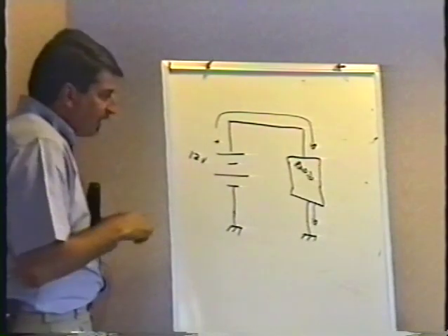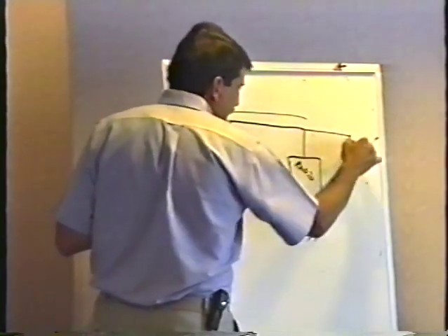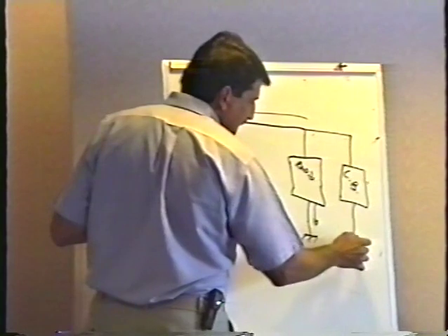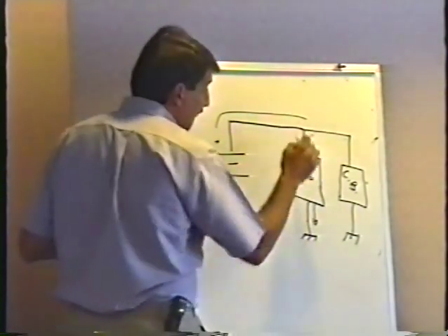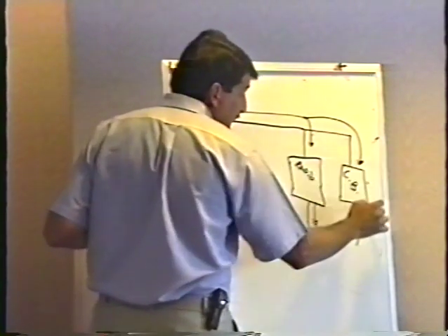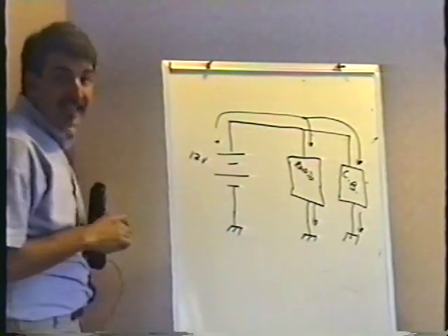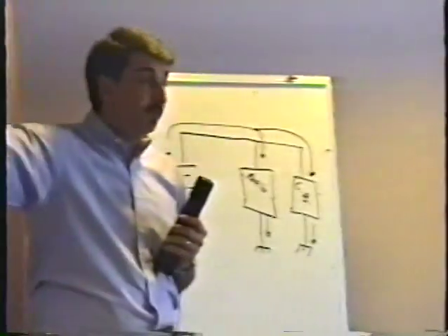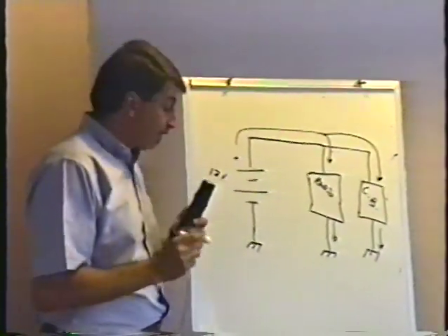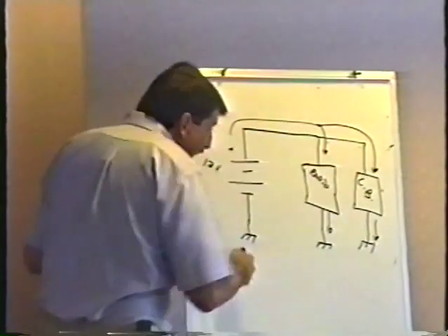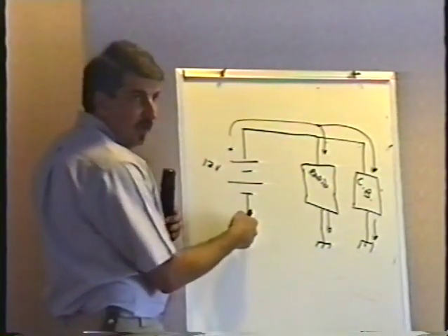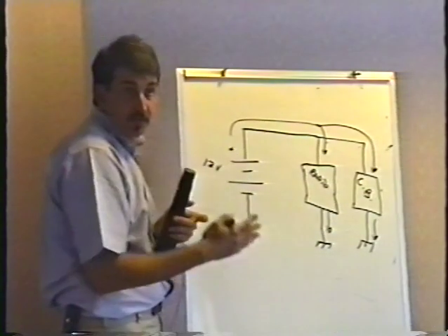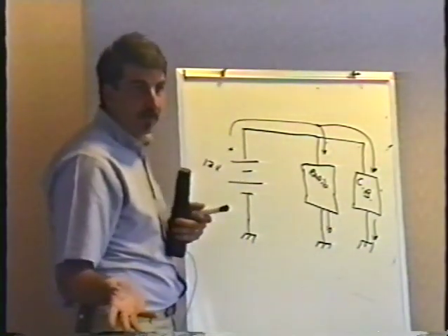When I draw ground in 2 or maybe even more different places, like, for instance, it not only goes to the radio, but I've also got a CB rig, right? That side of that would also be grounded, right? That's the return path. The current flows into the radio, but current also flows into the CB. The return is back through ground. There's lots and lots of things in a video game, a monitor, a pinball, whatever, that are connected to ground. And instead of having a wire going back to a central ground, which would be really complicated and the schematic diagram would be a mess, they put a ground symbol everywhere that it goes to ground. But everybody can see that these are all connected together, correct? All right.